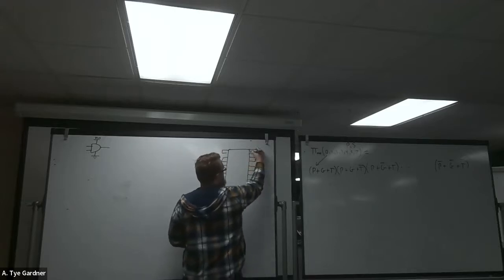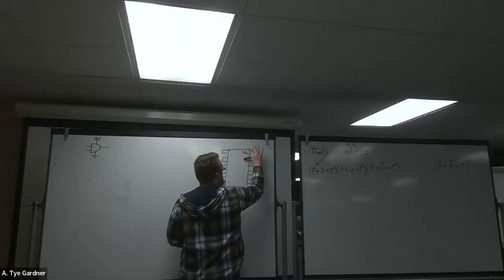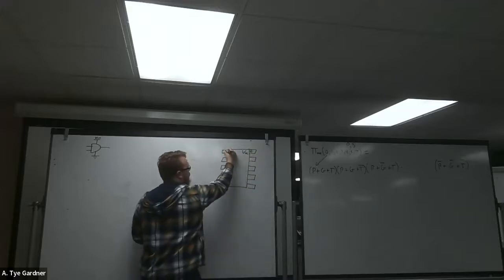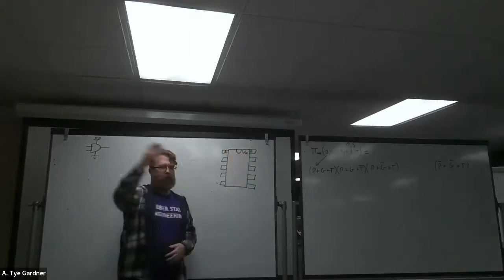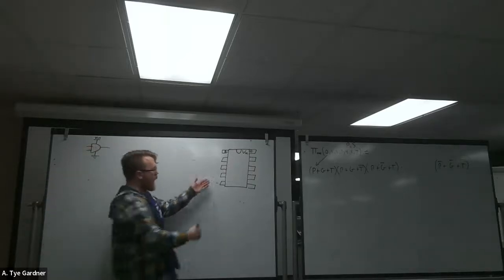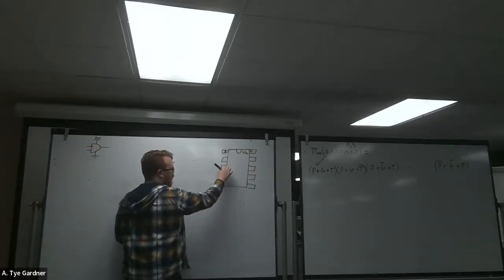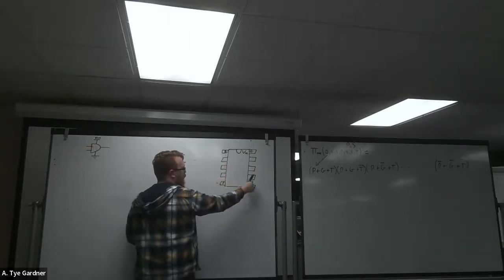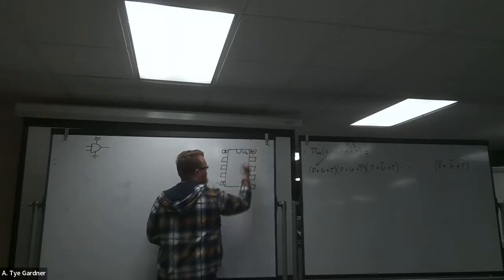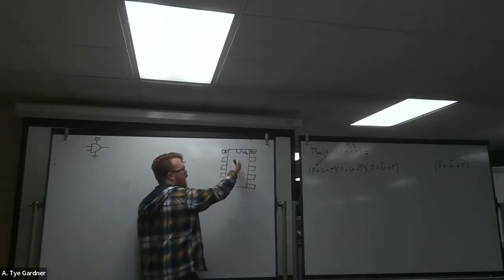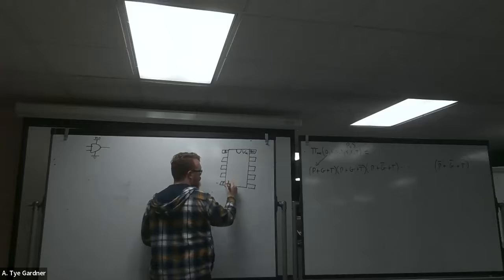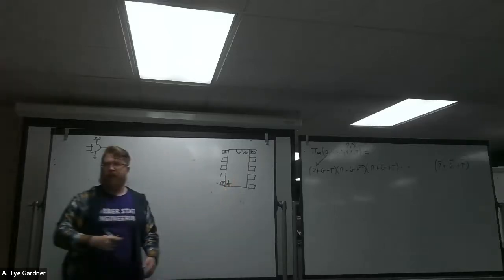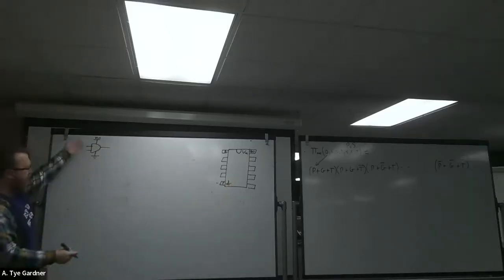this one, so this is pin 1, right? The top left, and they have that physical indent to orient you on where it is. And that's pin 1, and it counts down to pin 1, 2, 3, 4, 5 in this case, 6, 7, 8, 9, 10. And in the last one we used, this was VCC, and that was ground, right? So that it knows what they are and it corresponds to those.